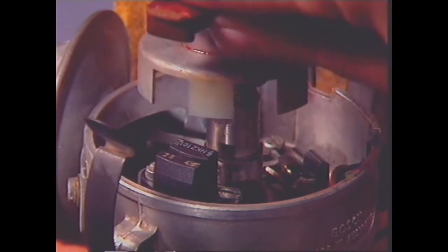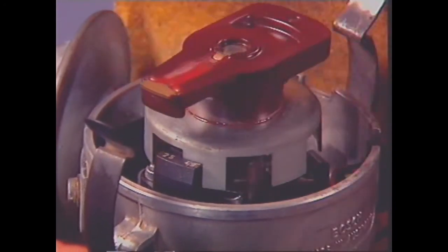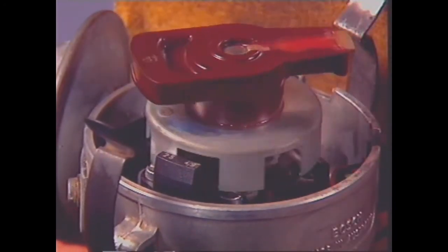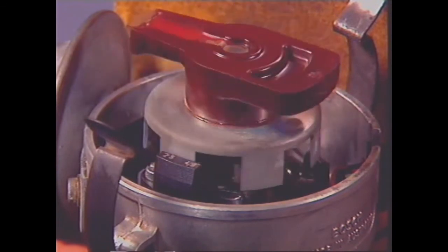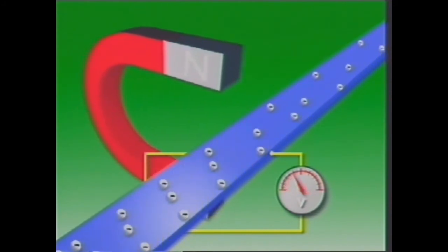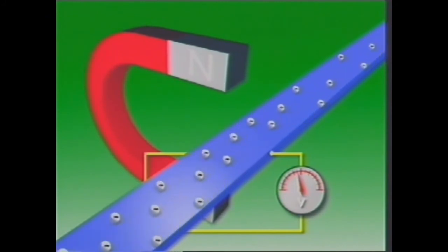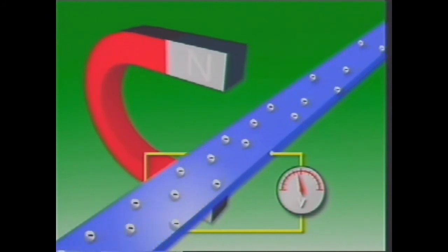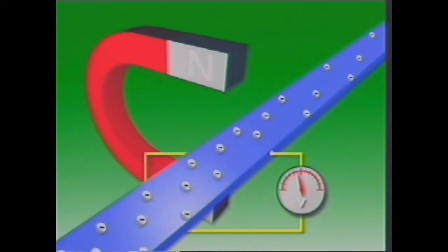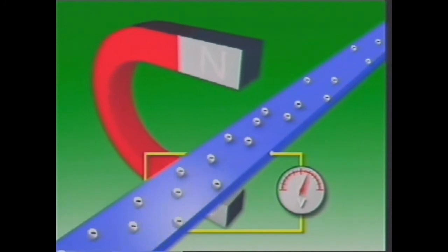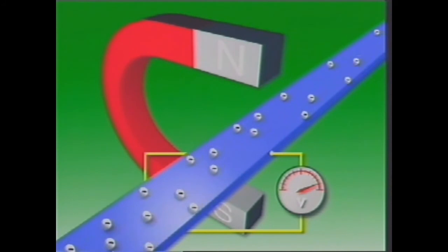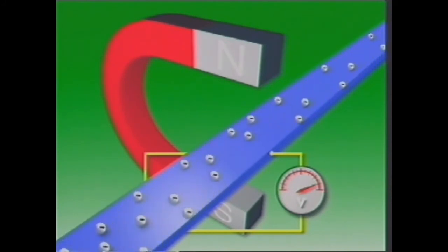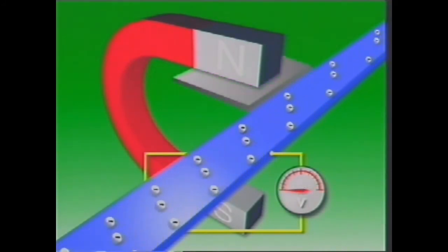Hall effect generators operate by using a potential difference or voltage created when a current-carrying conductor is exposed to a magnetic field. If a magnetic field is applied at right angles to the direction of current flow in a conductor, the lines of magnetic force permeate the conductor and the electrons flowing in the conductor are deflected to one side. This deflection creates a potential difference across the conductor. The stronger the magnetic field, the higher the voltage. This is called the Hall effect voltage.